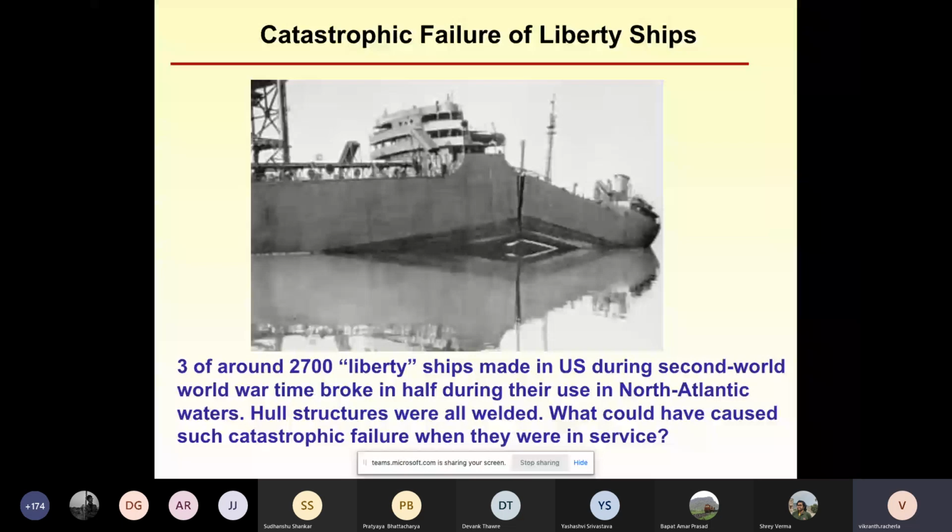So it was fatigue failure. No, fatigue is repeated loading over a period of time, and fatigue failures normally would not be catastrophic. They would slowly progress and then lead to final failure. So maybe it is the corrosion failure. The temperature of the North Atlantic waters is quite low. Like specifically the levels of temperature for metals: you take aeroplanes. Aeroplanes are flying in air, and when they are 10 kilometers above the Earth's surface, the temperature over there can get to minus 20 degrees C and all that.